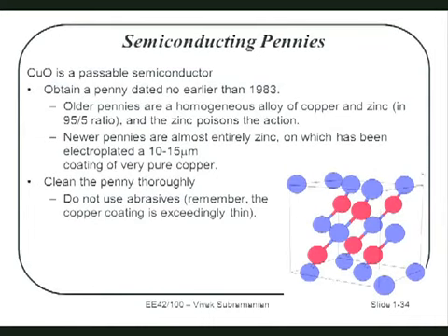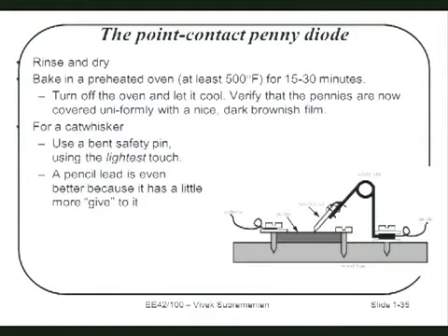If you take copper and clean it, by rubbing it very nicely with something soft to get rid of the oils, and then you oxidize it. What you do is you clean it and stick it in an oven and heat the oven up to about 500 Fahrenheit, maybe a little bit longer. Many ovens don't get up to 500 that well, so you can crank it up or put it on the clean cycle for an extended period. And this is why you don't want to do it in your oven, do it in someone else's oven, okay?